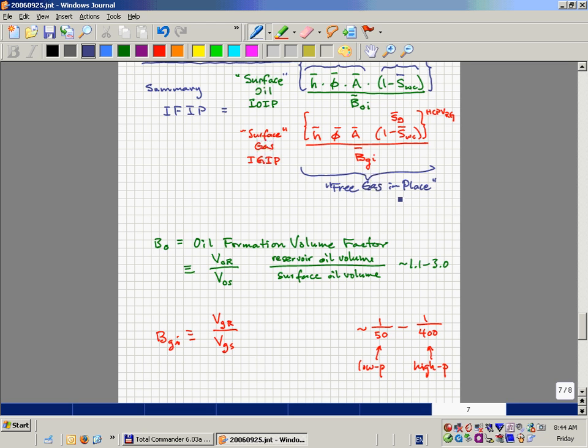What we have to do is add a second term, which is the initial oil in place times what we call the solution gas oil ratio. Rs is the solution gas oil ratio. All of the gas oil ratios in petroleum are written with the term R, GOR, and its symbol is simply R.